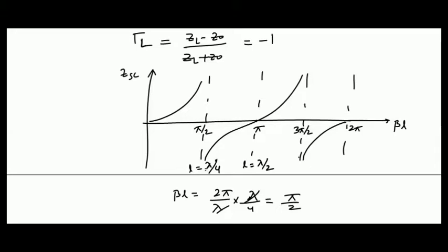In this way. So what we observe here is that we can use a short circuited line as circuit elements. If the length of a short circuited transmission line is chosen such that it is between 0 and L equal to lambda by 4, then that particular transmission line can be used as an inductor because its input impedance is inductive. So we can use the short circuited transmission line as an inductor or a capacitor based on its length.